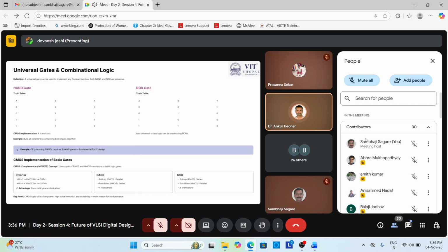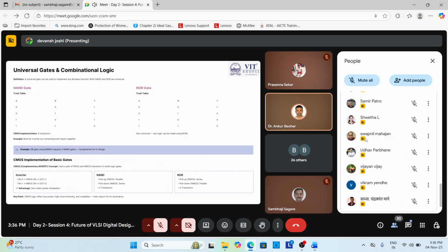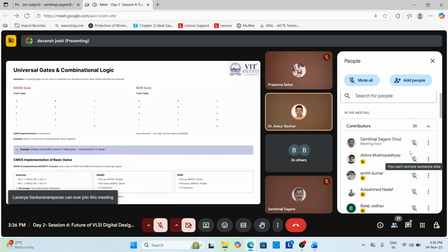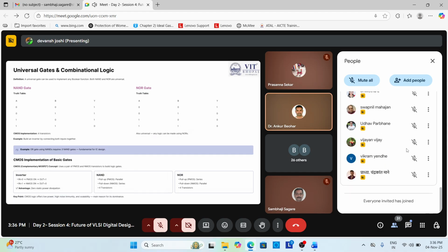So here we found the pull-up network and the pull-down network, where the pull-up network is implemented by the PMOS, while the NMOS implements the pull-down network. With the help of these both structures, we find the parallel and serial combinations in the inverter circuit. Here is the CMOS implementation by connecting the inputs together, and how we can implement the basic circuit with the help of the devices and their coding and implementation in Verilog.